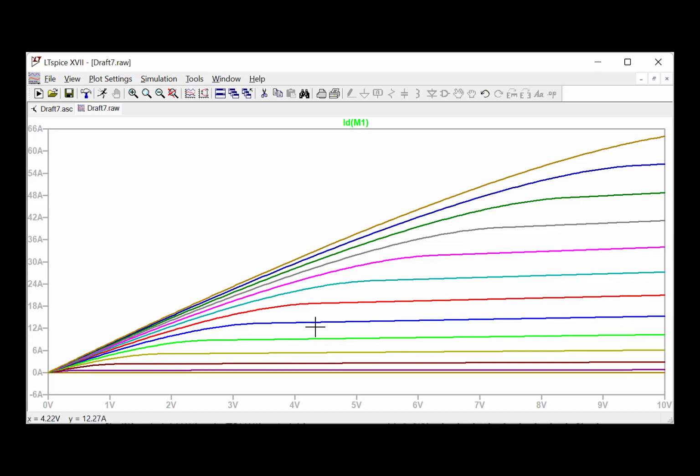And then we have a second regime, which is called the saturation regime, where basically the current is reaching a fixed value, which depends mostly on the bias point that has been defined. In this way, we can also understand that with increasing gate voltages, of course, the transistor starts from a condition when it is off and gradually turns on until reaching a relatively large current.